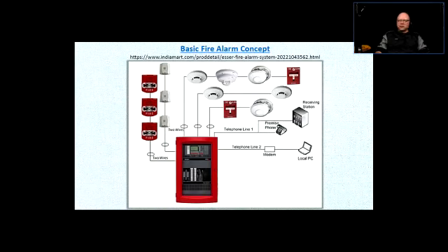In the fire alarm, the zone is not open, not closed to be at rest, but it has to see a resistance, a certain type of resistance that we are presenting it in the form of something that's called an end-of-line resistor. And we'll talk about that in about a couple of minutes. All right, so what do we see here?